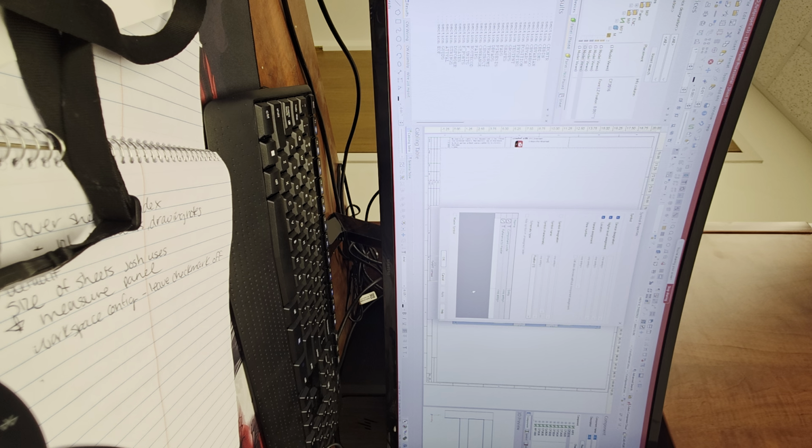Symbol properties, okay, and the part that you will be using to make them invisible is this level option that you see as position 1. Everything that you ever draw in DTM, schematics and panel, is by default this position 1, unless you want to put an object or a level somewhere else for different purposes. So if you scroll all the way down to the bottom of this list, there's something called construction layer, or even hidden panel plate, for example, 254, the second to last one. Click on that, 254, and click apply and OK.